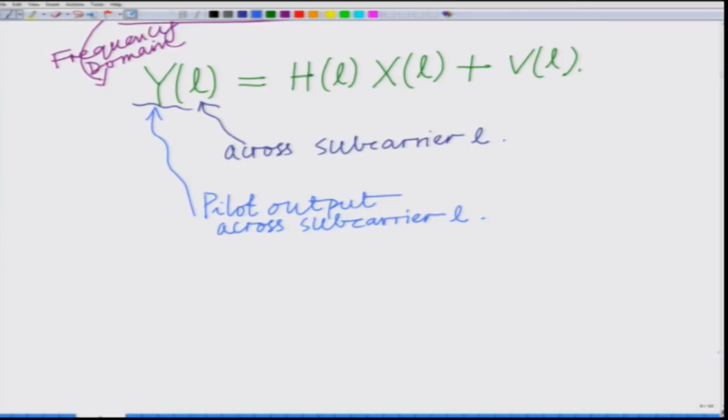So, what we have done so far is we have considered a simple n equal to 4 subcarrier OFDM system. We have loaded the symbols capital X0, capital X1, capital X2, capital X3 onto the subcarriers, that is, performed the IFFT or the IDFT to generate the time domain samples, added the cyclic prefix, and we looked at what happens at the receiver once you take the FFT.